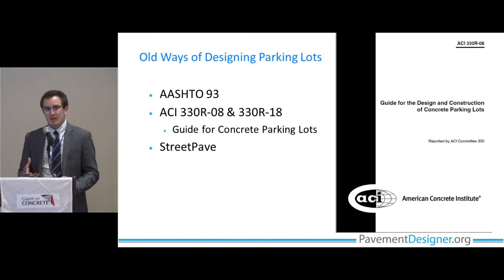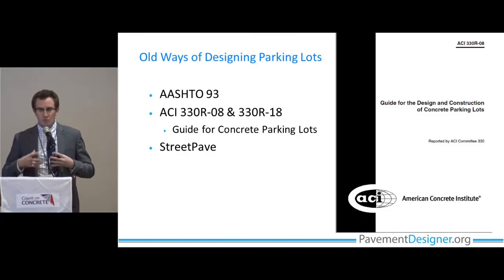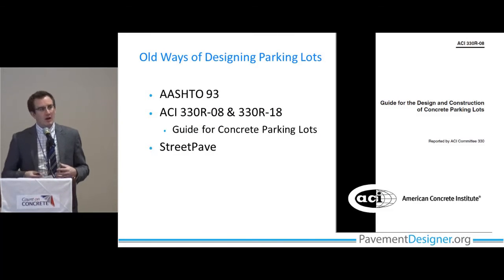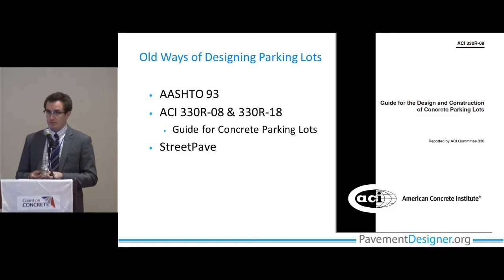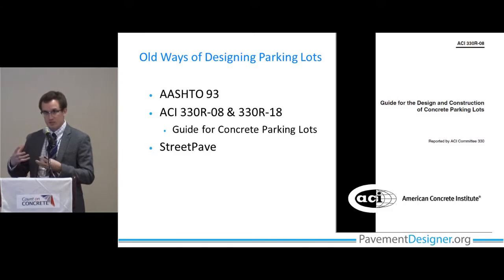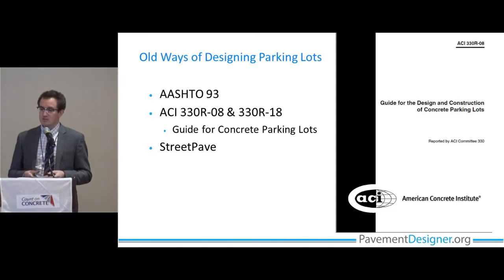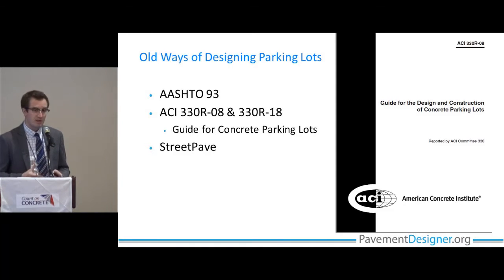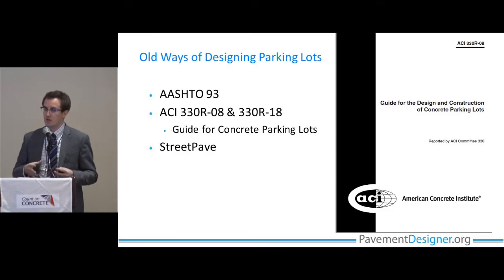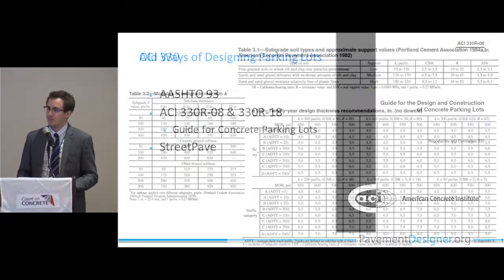When we look at parking lot design, and I mentioned that this is one of the gaps that we were trying to fill, the main ways that you could design for parking lots were originally AASHTO 93, which is supposed to be a highway design. You could design with ACI design documents, which we'll step through in a minute, or you could design with StreetPave. Now, StreetPave was actually the predecessor for Pavement Designer. It's actually what's powering a lot of the design within Pavement Designer, so that's already featured within the design.